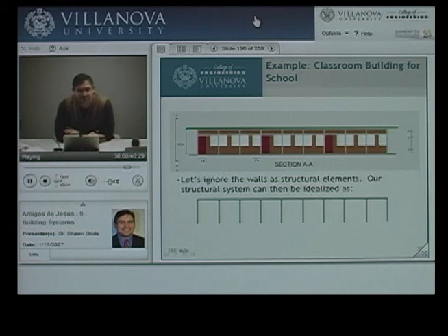But what we're doing is actually providing more resistance than is actually necessary then, because if I happen to remove those walls, or I didn't build the walls correctly, or if I didn't have the walls tied into the rest of the structure, I'm not going to have a lost or a broken load path. I'm still going to have a path through this system that allows me to take the loads down to the foundations.